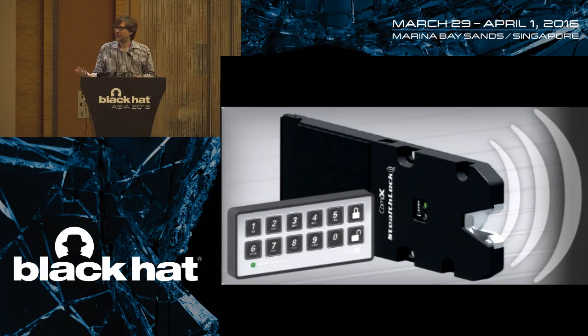First thing I did was fire up a HackRF and observe the radio signal, and I found its signal, and I observed very clearly that when the LED lights up, it's transmitting. When I put the battery in, it immediately starts transmitting for a couple of seconds. And then after that, when I'm punching buttons and hitting lock and unlock and so forth, it never transmitted again. It only transmitted right when I put the battery in, which seemed to be wrong. It didn't seem to be behaving the way it was supposed to.